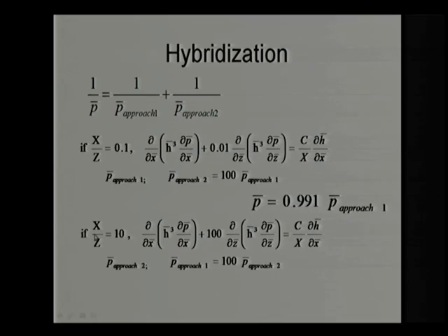Similar is the case when the dimension in the x direction is large. So, the dimension in the x direction is 10 times large compared to the dimension in the z direction. In that situation, we neglect this and it is equal to 0, and this side remains. Whatever pressure profile comes, we represent as the non-dimensional pressure obtained by approach 2.